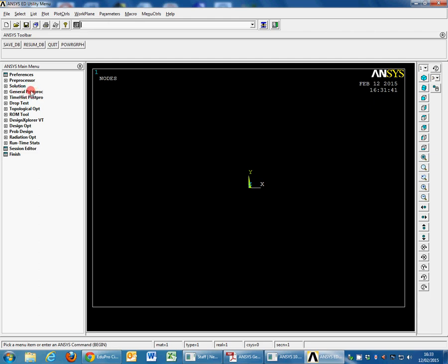Okay. So I'm going to use the method of direct generation. There is another method called solid modeling where you make volumes and areas and lines, but the problem with that is it's overkill for what we need. To create nodes and elements in space exactly where I want them, I might as well directly generate them. So this is the way I'm going to go with this particular model. Okay. So first of all, I'm going to enter the preprocessor.